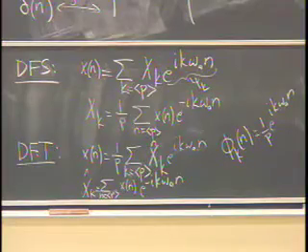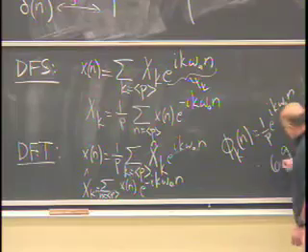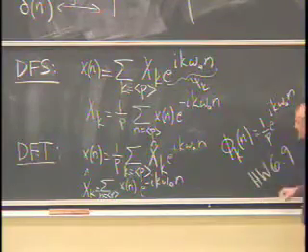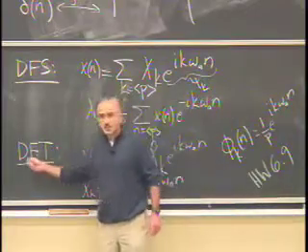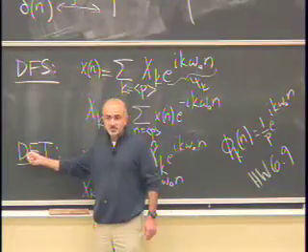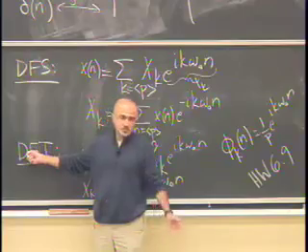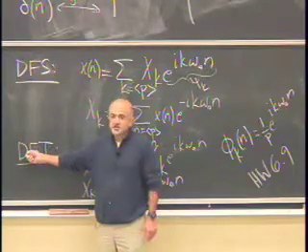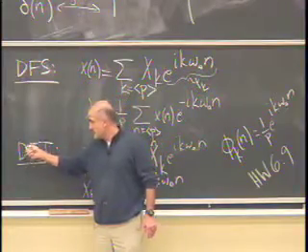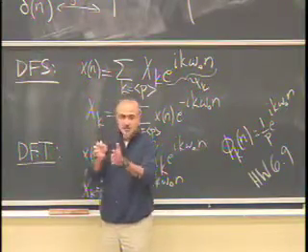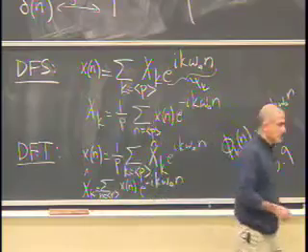But the methodology for all of these is the same. So look at problem 6.9 to see the relationship between the DFS and the DFT. If you've ever heard the term fast Fourier transform, that's essentially the DFT implemented using efficient algorithms. So the FFT is not a separate transform on its own. The FFT is the DFT executed in a particular set of ways that are efficient.